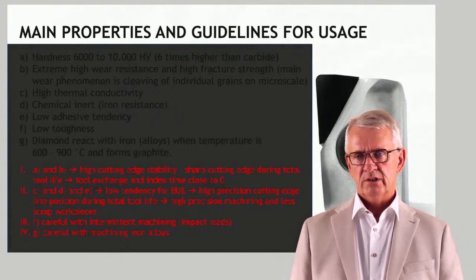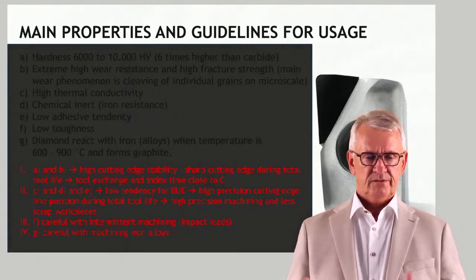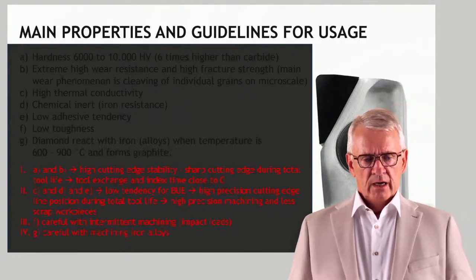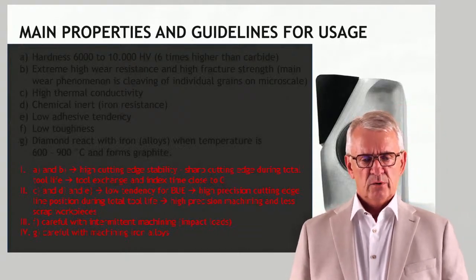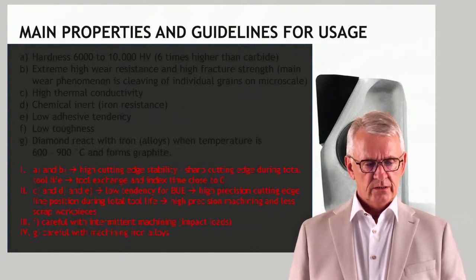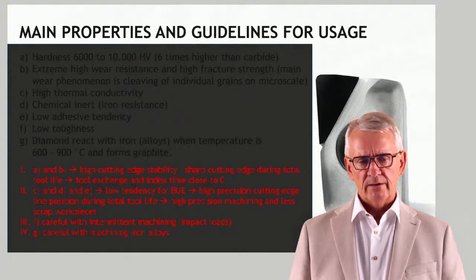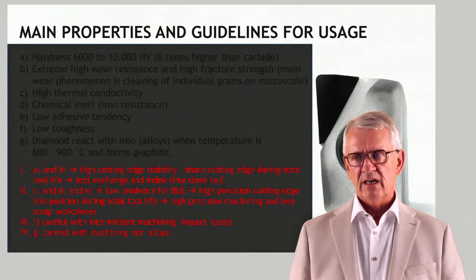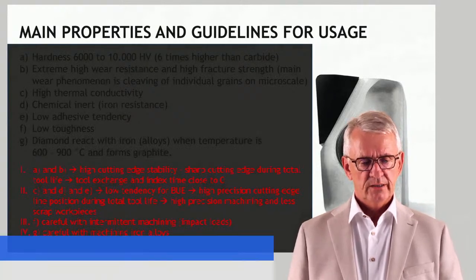With one tool, you can continue to cut and cut and cut, which is very favorable, for instance, for your OEE. They show a low tendency for build-up edges. So you can do high precision cutting during the whole tool life of the tool, which is good for high quality machining, hard machining, high precision machining.